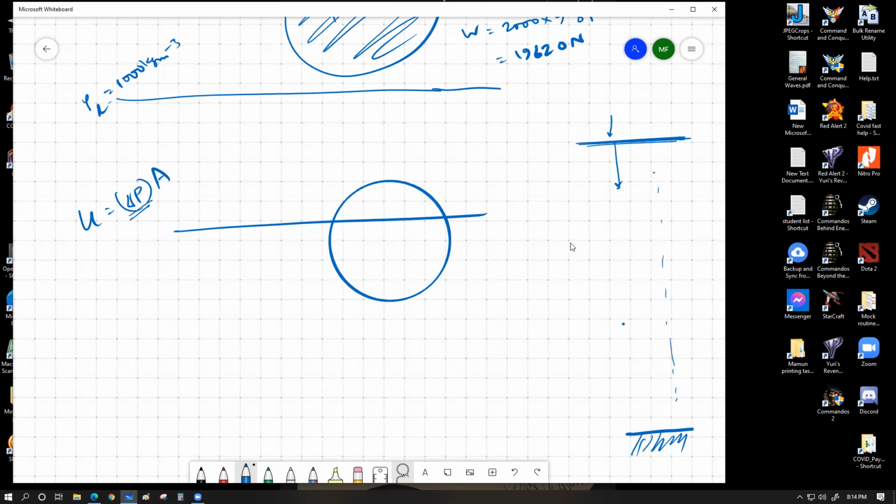What is the pressure at this point? It is equal to the atmospheric pressure plus the pressure produced by this height of the water. So the deeper you go, the value of absolute pressure will be definitely bigger. No question there. It's absolutely true. However, if you have a spherical ball that has a fixed diameter and the difference between these two levels is not going to change,